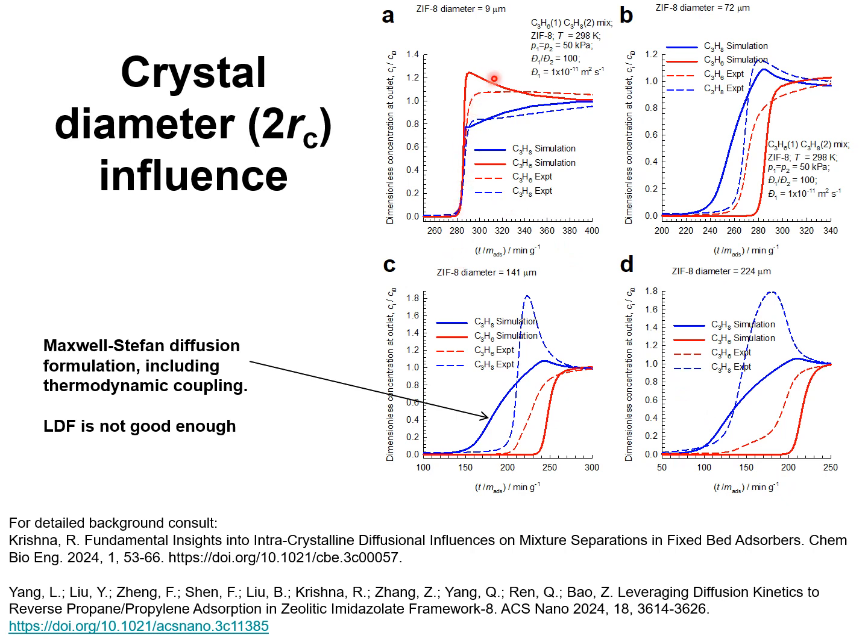And they show that with increasing particle diameter, the breakthrough of saturated propane occurs earlier. And that is important in PSA separation schemes, because the achievement of high purity of propene that is recovered in the vacuum blowdown step is higher if propane is practically excluded from the pores. Therefore, increasing particle diameter is desirable.